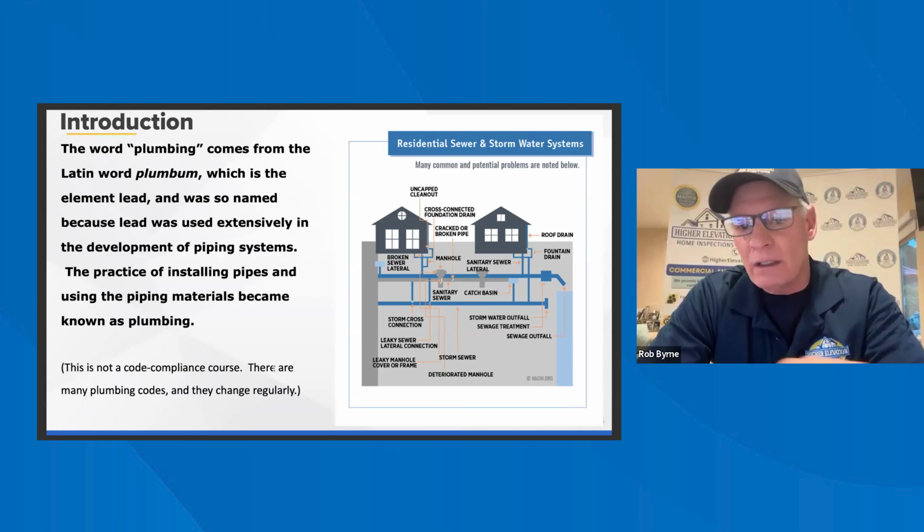This is just temperatures of how quick you can get burnt. If you see, when you're running the hot water, that it's steaming, and you shoot it with your infrared or thermal imaging camera, identify those temperatures if they're high. You don't have to put the exact temperature, but just say higher than required or recommended. If they have little kids, they can get burnt real quick. So it's important to know the temperature of the hot water.